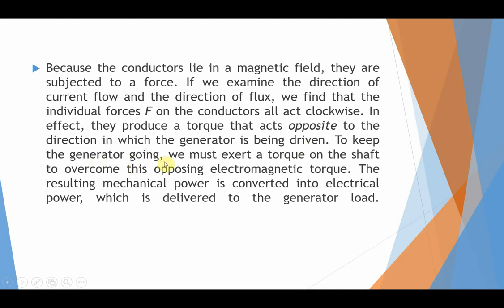To keep the generator going, meaning in running condition, we must exert a torque on the shaft to overcome this opposing electromagnetic torque. The resulting mechanical power is converted into electrical power, which is delivered to the generator load.